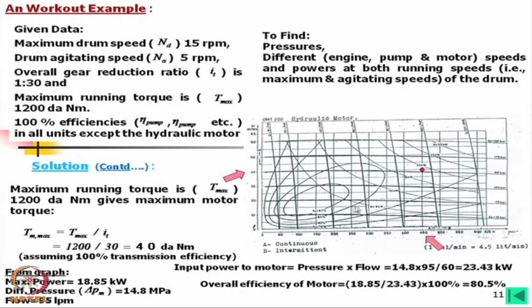If the motor operates within this zone, it is 85%. If it operates within this zone, then you can say something between 80 and 85%. We can see this is 80.5. This is the 80 line, but it is coming to 80.5, maybe some estimation is slightly wrong, but if this is 85 and this is 80, it will be something in between, maybe 81 or 82%.